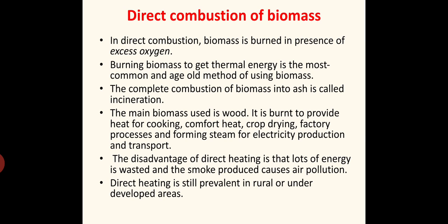As we all know, this is a low energy efficient process, because a lot of energy is lost during this direct combustion process. Complete combustion may not be possible, and it also produces a lot of pollutants. Carbon monoxide, carbon dioxide, everything is produced during the combustion, and this will be a pollutant for the atmosphere. So these are the drawbacks of direct combustion. In direct combustion, biomass is burned in the presence of excess oxygen. That is the important point.